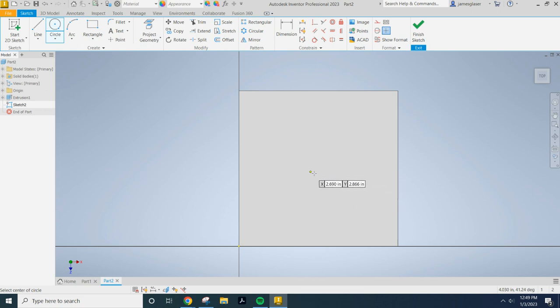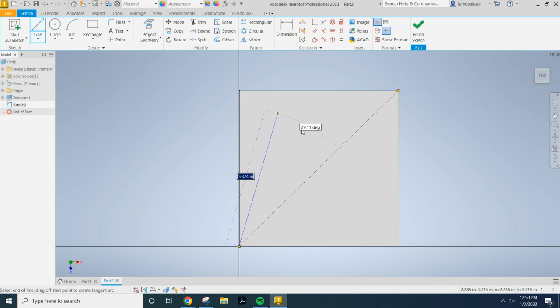Sometimes it'll pop up and have a little green point there if your settings are correct, but most of the time those settings are off, so you have to do it the old-fashioned way of finding where the center is. To do that, click your line tool and then click this button to make a construction line. And then you're going to hover over to this corner. You see how it popped green? Coincidence constraint again, and then come down here to that corner. Let it go green. And now you see how it's wanting to drag another line out?